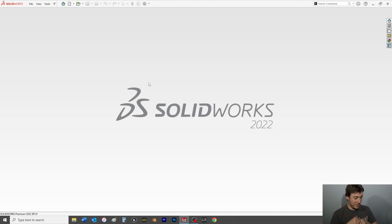From here you will be, of course, selecting the units and the dimensional standards from which you want to work with. For me, I chose inch, pound, second because I'm in America, and ANSI dimensional standards for now. And then I've clicked OK. And once you do that, that prompt will no longer appear when you open up SOLIDWORKS. But don't worry, these settings can be changed at any point, and I will later show you many different ways in which you can do that.